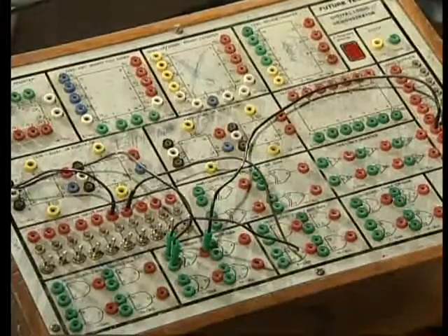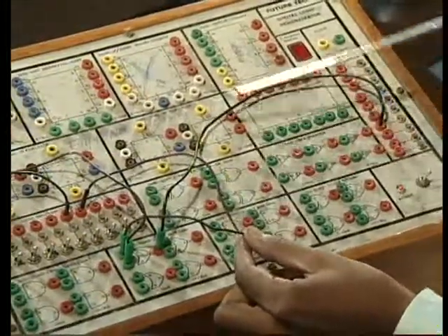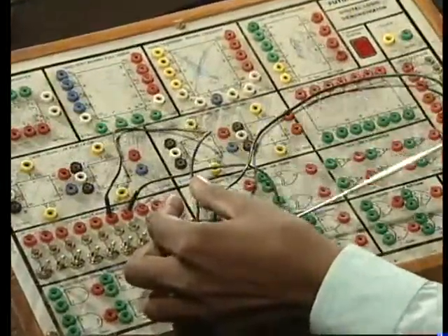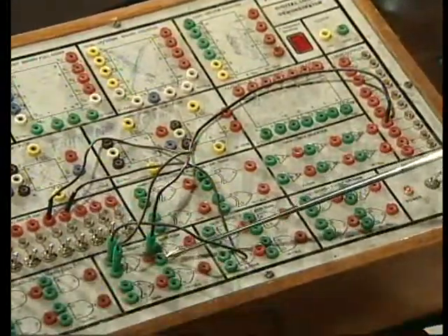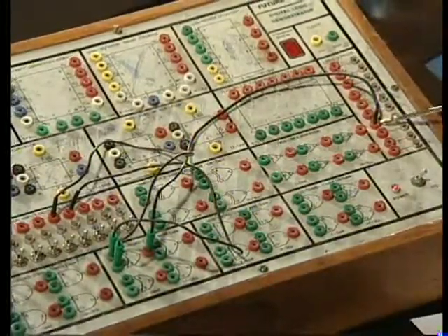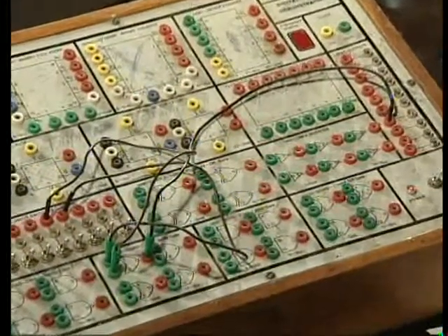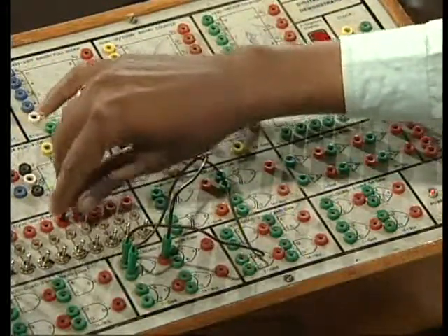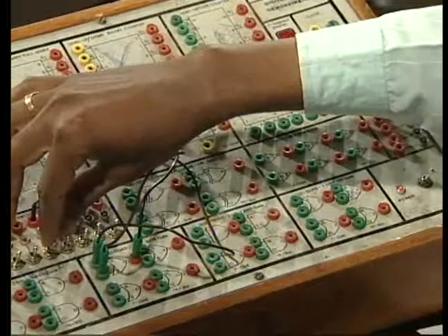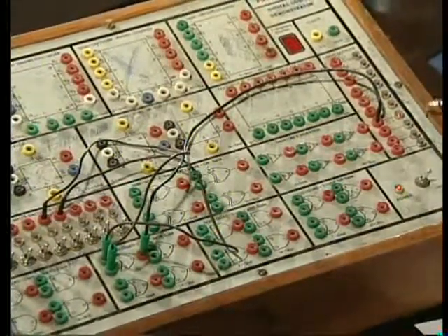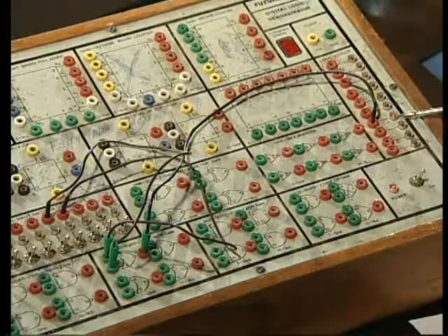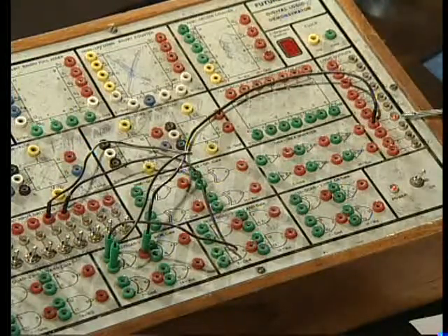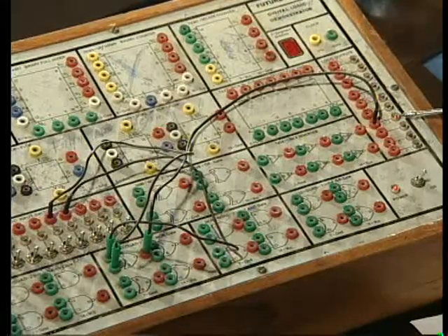Now, see here, the 2 inputs are connected to the input slots and the output from pin number 1 is taken and put in this slot. Now, we shall give the various combinations of the inputs. At the beginning, both the inputs are 0. Under this condition, the output is glowing, that is logic 1. When the inputs are 0 0, the output is logic 1, that is high.